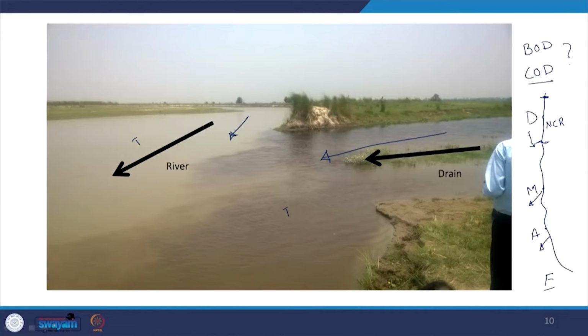So, that is something to keep in mind, as in even though I might not be concerned about the long term effects, if I let this persist downstream of this junction of the river and drain, remarkably septic or anaerobic conditions will prevail, and that is going to kill the ecosystem in that particular region, right. And you are also going to affect the quality of life of the people around, and also the fishermen and such, right. So, that is something to keep in mind.